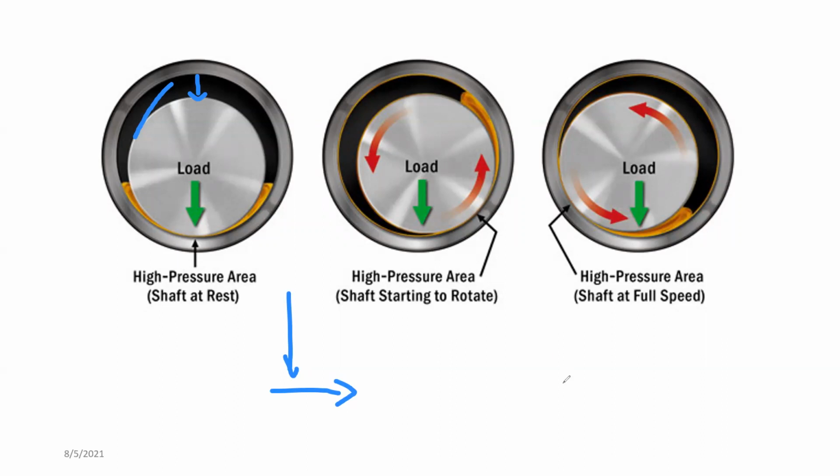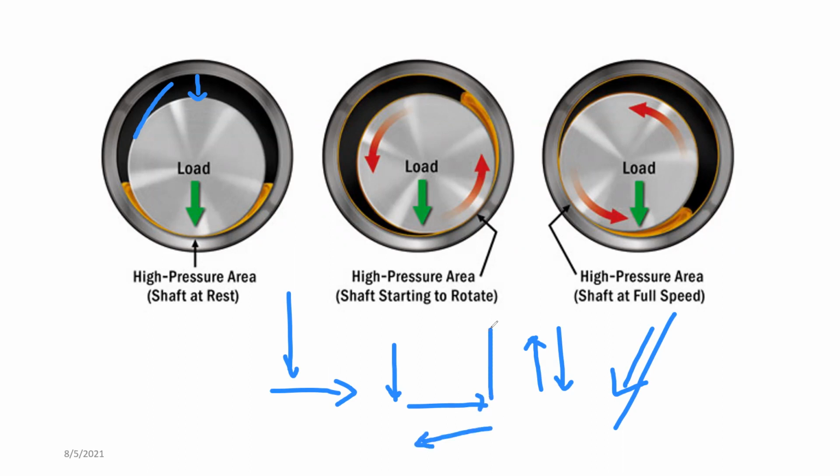Even though the piston is moving up and down, the connecting rod is not moving up and down. It goes on an angle, so that force is transferred into two components, one downwards and the other sideways. When it goes the other way around, it goes in reverse. So these forces move the crankshaft around, and we can't actually see it.